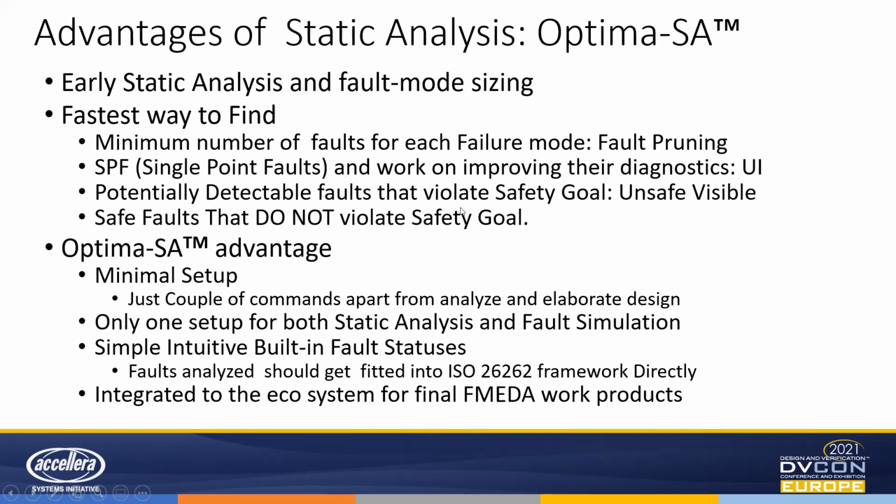And potentially detectable faults that violate the safety goal. This is what is unsafe visible, and this will give you the diagnostic coverage. And safe faults that do not violate the safety goal. One of the important takeaways from the safe faults is that if you have designed and you know that some parts can only be in this area, and by mistake some of the designers have put them into a safety critical area where it violates the safety goal, you will get to know by looking into the safe faults category.